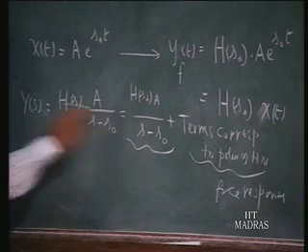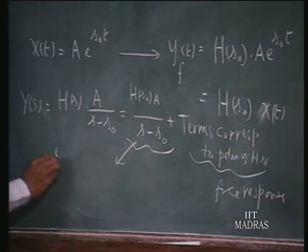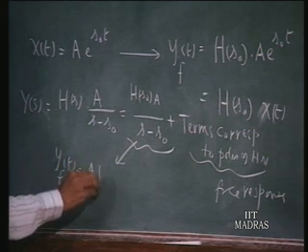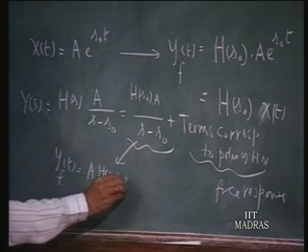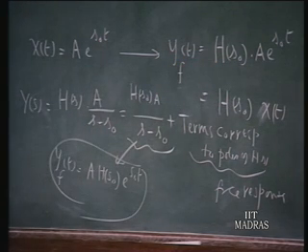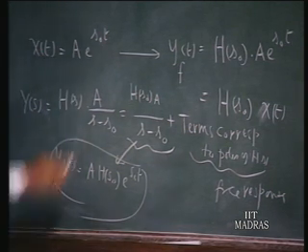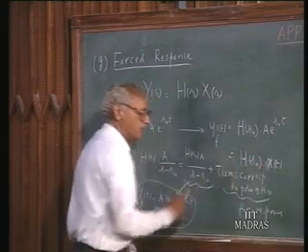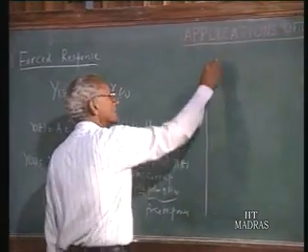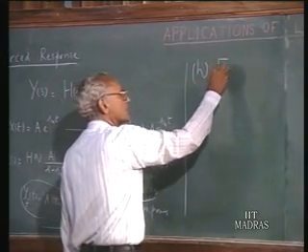And so from this, the time domain representation is y of t equals A times H of s naught times e to the power of s naught t. That's exactly what we said is the forced response. So this is how it ties up with the Laplace transform theory. What we already know from your preliminary lectures, whenever an exponential signal is there, the forced response is the input times H of s naught. Now, arising out of this, we can talk about the frequency response characteristics.